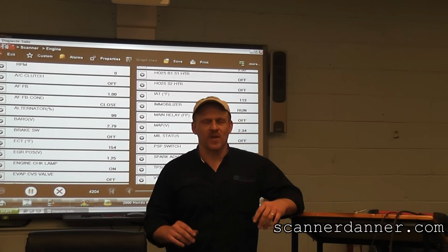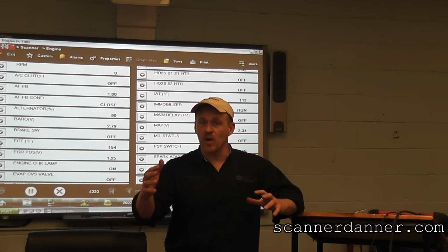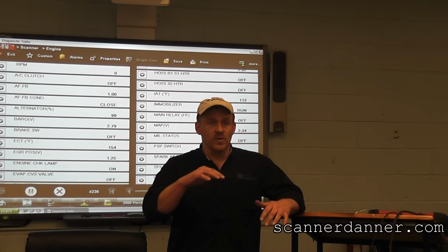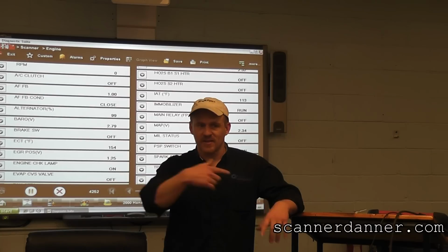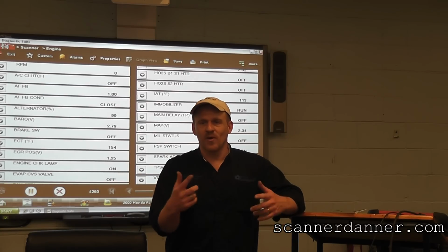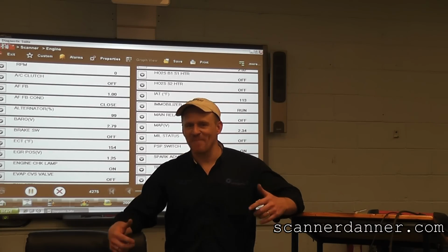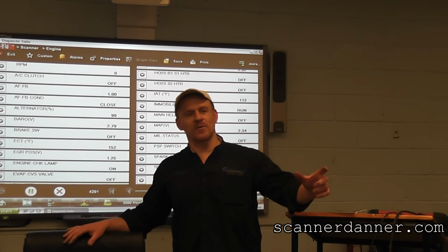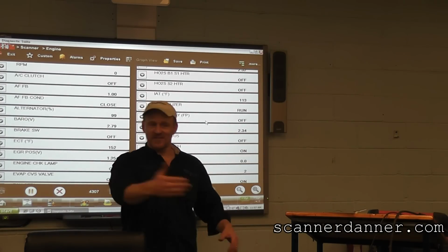Anyway, before lunch I mentioned when you have a MAP sensor that's reading load conditions, wide open throttle, at idle, that generally it'll run good under a load, but not at idle. And I said this one's not reacting that way. Well, of course it wouldn't if the TPS is the MAP and the MAP is the TPS. The MAP signal's never moving. The resistance value of the TPS is off compared to the MAP sensor, so it's reading a load constantly.